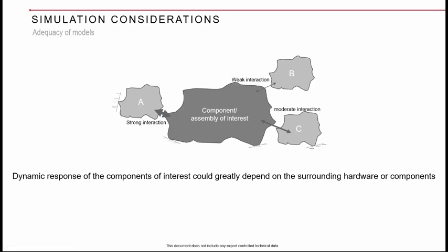So the harness being a flexible member, when my component unit is vibrating there will be only a weak link of interaction with the electric harness wires. The electric wires being flexible won't contribute much to the dynamic interaction between these two components, so maybe I can ignore modeling that in my analysis. Similarly, when I have a metallic tube which is clamped at a shorter distance, that can certainly influence the response of my component. The mode shape itself can be different, and the frequency can be slightly different. Not only that,